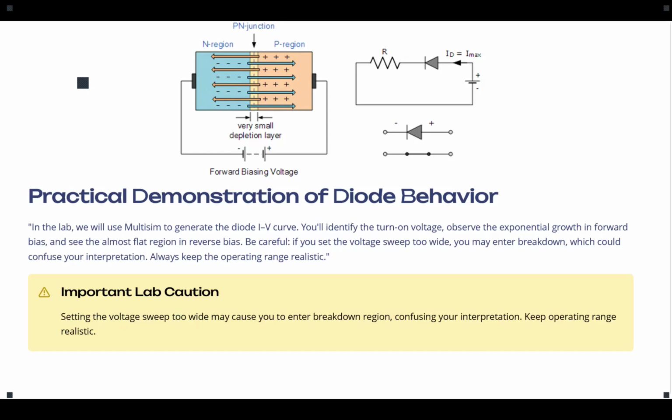Okay, when the voltage passes that V on, it is small enough that the charge can now jump over the depletion region, and now we have a current. On the other hand, when we have a reverse bias, the reverse electrical field we apply over the diode increases the depletion, so we are increasing the insulation part.